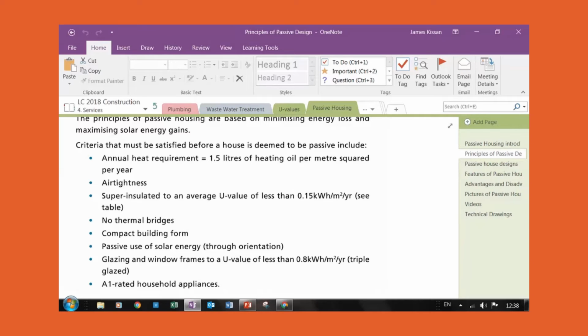Now, if you want to have a wood burning stove, the design is that you put a vent on your house, on the outer wall, bring in a pipe all the way into your house and bring it up next to the wood stove. So you open this vent when you have the stove running. That way you have combustion and you have oxygen for the wood burning stove to work. That's how you get air into the house if you want to have the wood burning stove. But in a lot of passive houses, you won't even have a wood burning stove.